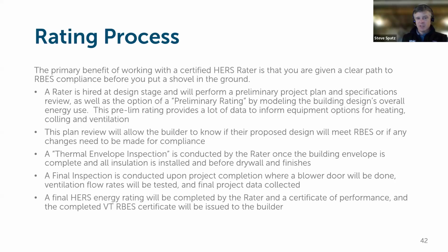And then a final inspection is done where the rater would come back out, capture the final as-built details and square footages, areas, et cetera, of the building if anything's changed from what the design plans had called for, perform a blower door test to verify the building envelope air leakage, and then verify the flow rates of the ventilation equipment as well, which is another huge benefit to have, of not only knowing that you have a ventilation system installed in the building, but that it's actually working as designed and you're getting appropriate flows room by room.